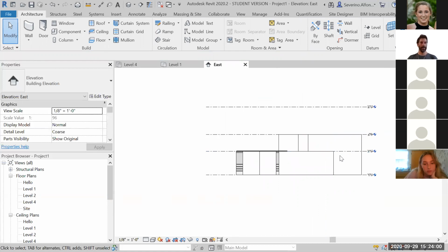Okay, let's spend another 3-4 minutes with this because I think it's very important. Again, create levels and make many walls of different types. Try different line configurations, polygon walls, curved walls, etc., and try to go from level X to level Y and change those levels, okay? And let me know if there are any questions. Okay, that's that.